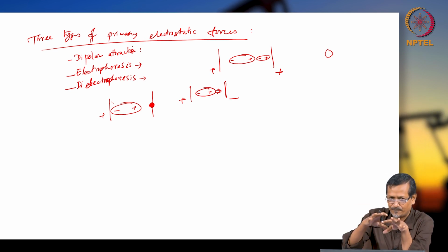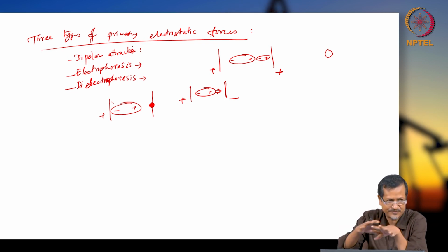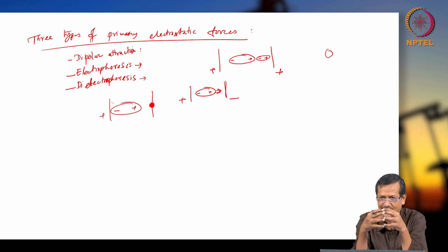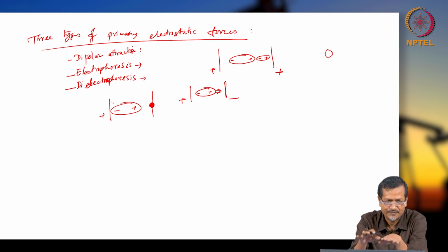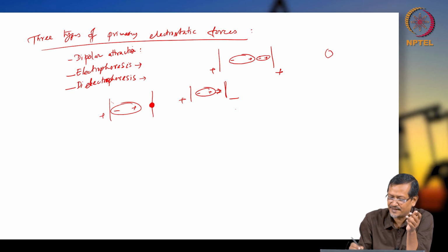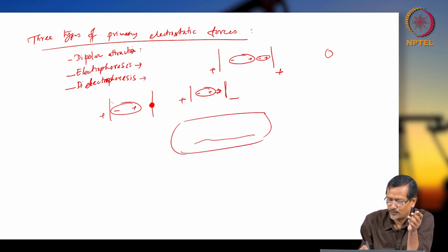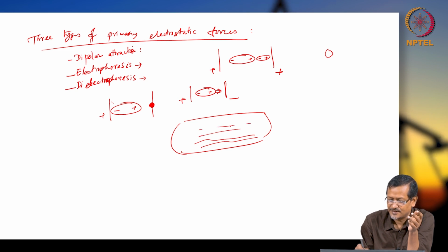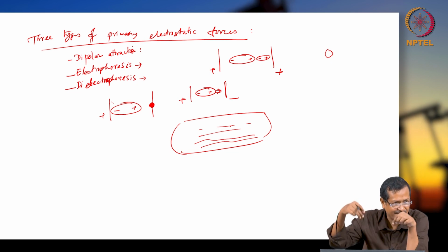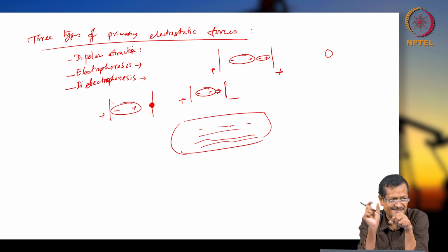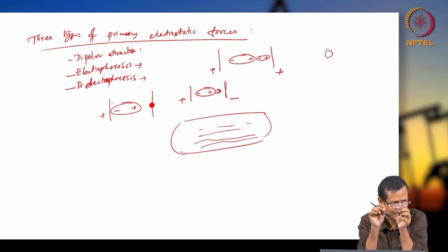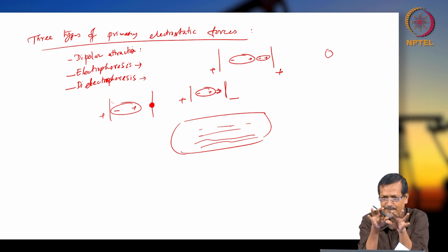So, if you have a higher amount of water, say in the lower section of the separator, you can use AC and create more collisions. You will create bigger particles, which will settle further down, and then you take them out from the bottom. But if you have DC voltage applied, let us say in a high bond separator, with one layer here and another layer here, in the lower portion the number of water molecules and water droplets will be higher. So there you apply AC voltage, give resonance, particle collision will be there, it will be distorting, and rupturing is possible of the surface coating agent, whatever emulsifying agent is already there.